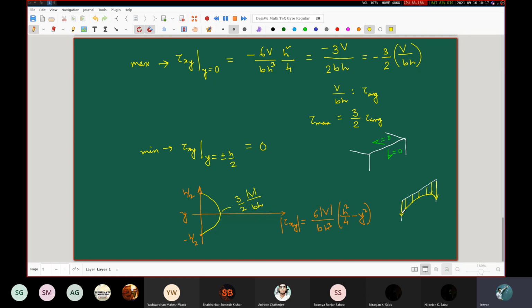So as I was saying, this shear stress distribution along the z direction looks like this. And you may be a little bit surprised to know that the maximum value of the shear stress along the z direction occurs on these vertical edges. The absolute edges. The minimum value is actually at this thing. We can try to go about finding this, but the current level of modeling that we have done will not enable us to obtain this distribution. So we will have to appeal to theories of elasticity, which you will study later on, probably in your 4th year, which will enable you to obtain this distribution.